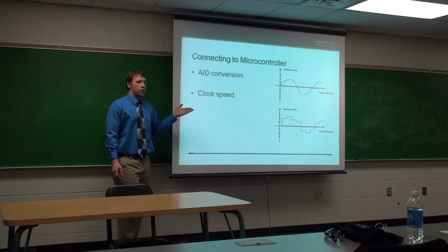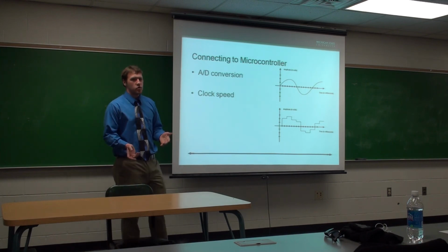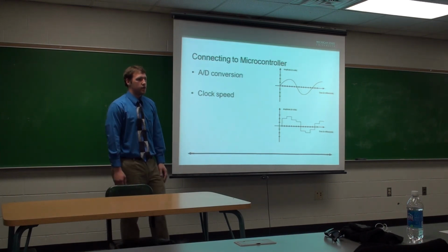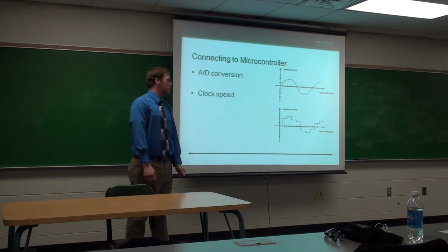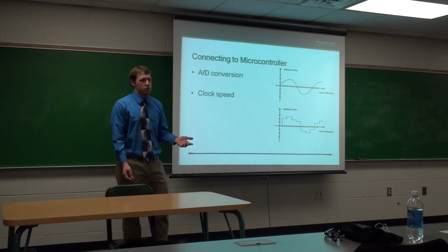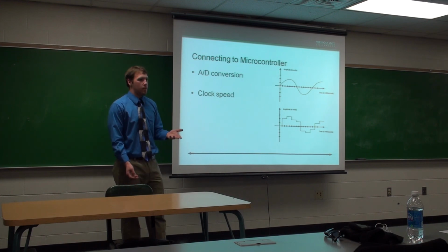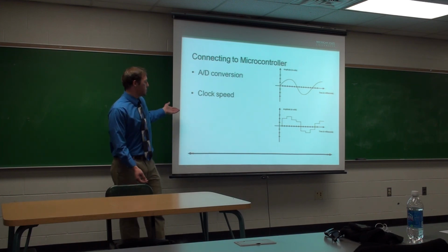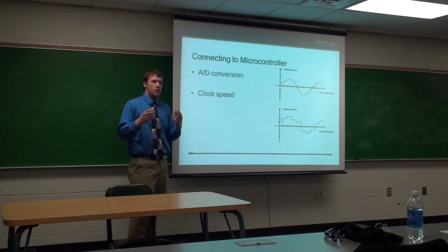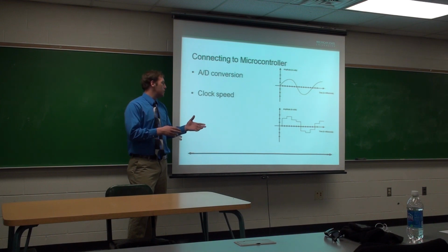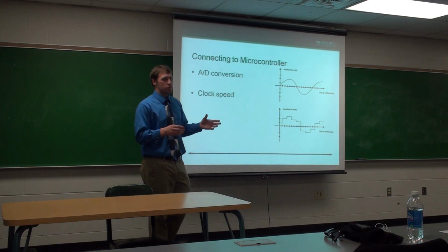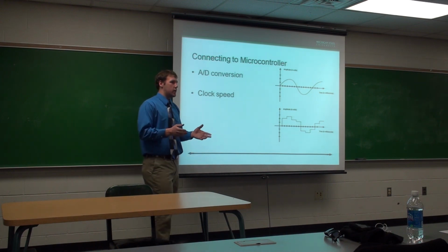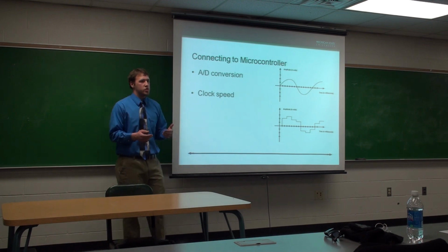Another issue is your clock speed of your microcontroller. Again, microcontrollers are made to withstand a lot of different multitasking capabilities, and the clock speeds are adjusted for that. So your clock speed of a microcontroller may or may not be your biggest concern, but it's something you have to consider. So you have a microcontroller that can keep a timer going, keep your output being outputted, and make sure that all your comparisons from your pressure sensor, in our case, are being taken in real time as opposed to a sort of lag, which may lead to unintended results when you get into the lab environment.